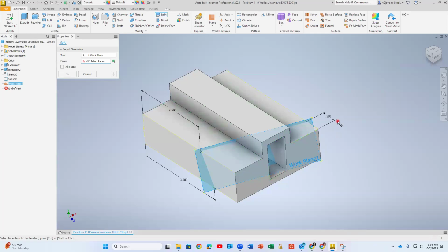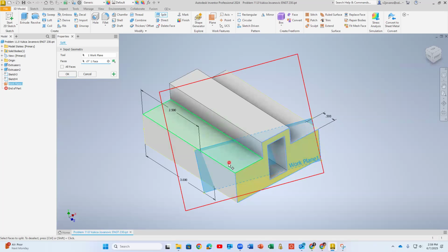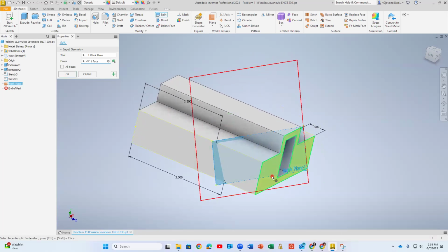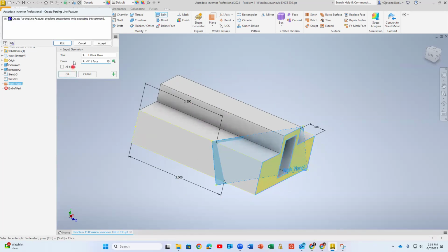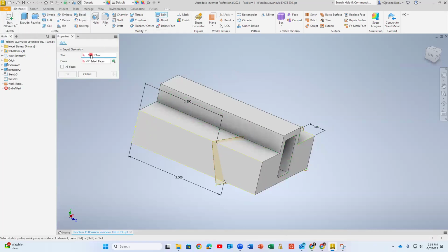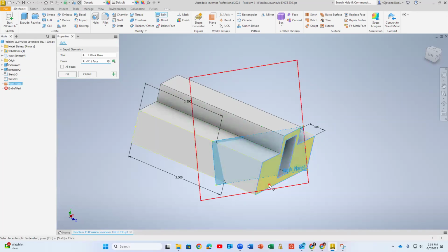Okay. And then left click on the right side face here, probably because we have to say what are we removing, which side? So, you know, I click over here, that's obviously on the other side. And if I say okay, no, there's something else we need to do. Okay, again, split, select tool, we select what we made. For the face, we select there, and then left click on the solid selection icon, keep side.